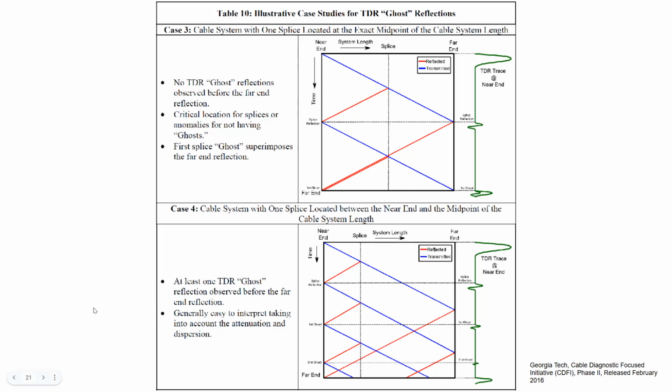And normally we have the data of cable systems, unless a cable was buried 50 years ago. In that case sometimes the data may be lost, but normally we know how many joints there are in a given cable system, because the utilities maintain this data whenever new jointing is done. So using that data, as well as carefully studying the distance of the first reflection and then the second and subsequent reflections, we can easily conclude that these are the ghost reflections.